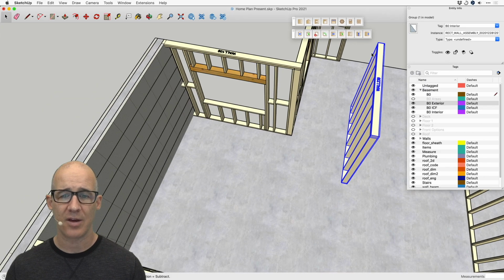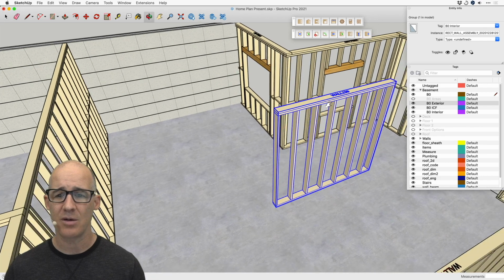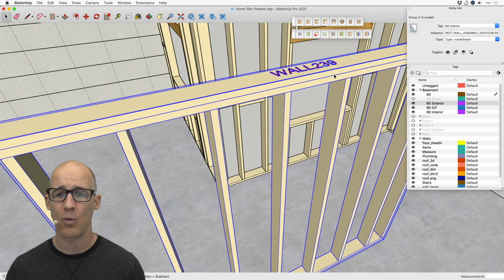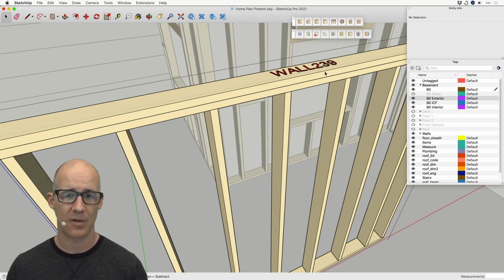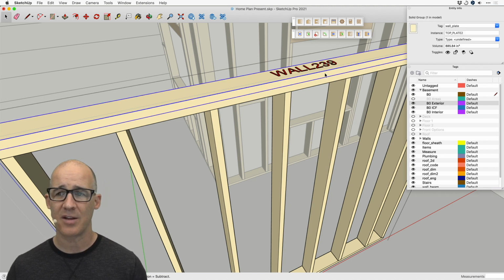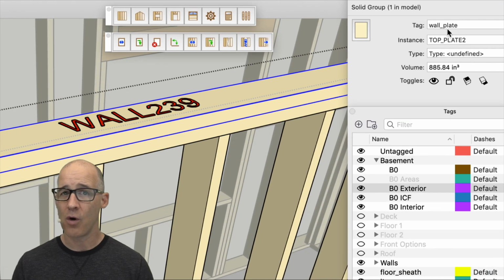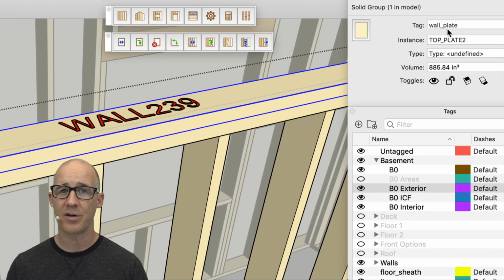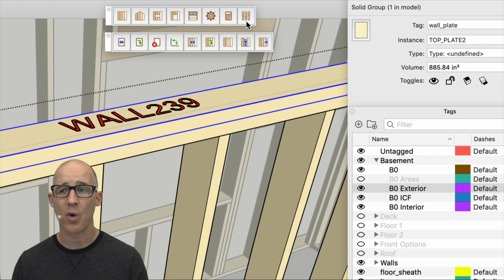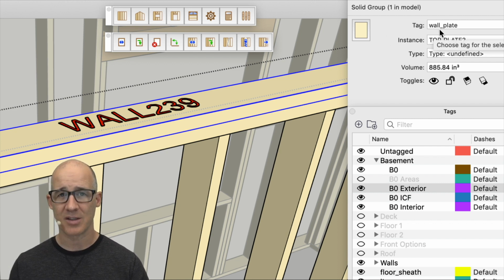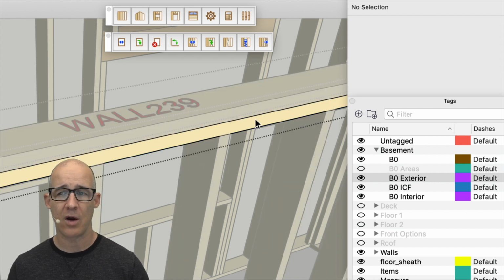When we look at this by simply drilling down into the object and zooming in, and when we double click and go into our edit mode of this particular group, when I select this, we can see that, as we saw before, one of the important things that we want to turn on before we even start using the Medeek plugin, within the settings of the Medeek Wall plugin, is we want to turn on all layers. So when we get all of those layers assigned, each object gets its own layer. So then we go to this one.